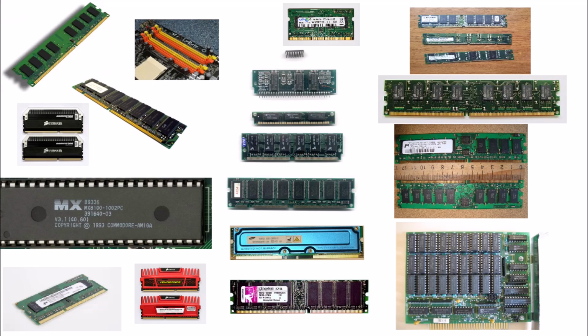In addition, so-called external cache memory, called L2, is placed on boards. For this purpose, very fast static RAM memories of small capacity, 256K to 1M, and short access time of several nanoseconds are used. Special integrated controllers are now being manufactured that control the operation of the cache memory.